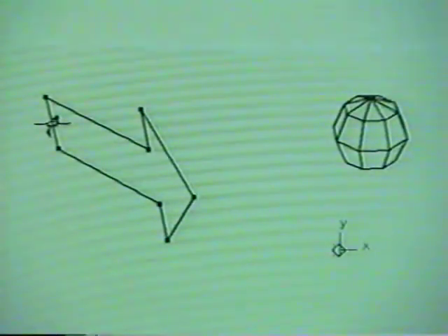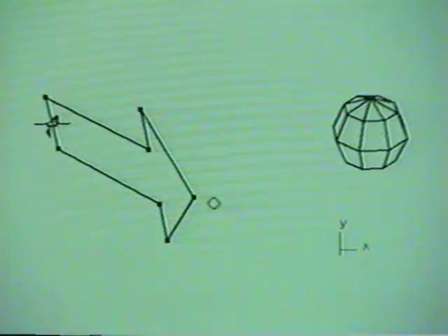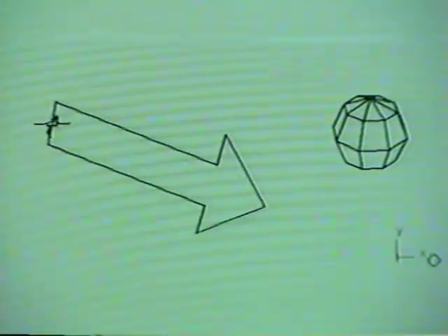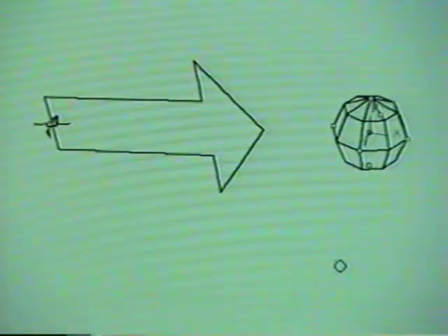Snapdragging can be used to form precise relationships between objects that are far apart. For instance, to make the arrow point at the center of the sphere, I place the skidder at the tip of the arrow and rotate the arrow about the midpoint of its tail end until the skidder snaps to the center of the sphere.